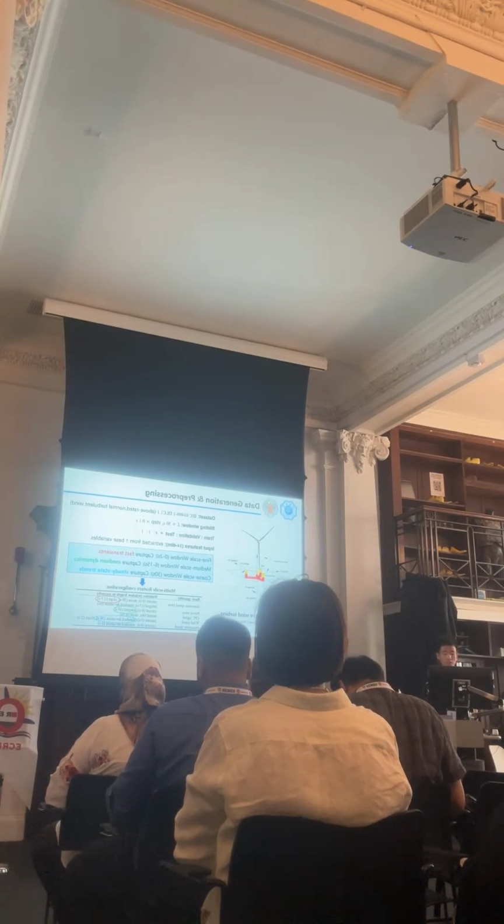And the third one is a coarse-scale window of 30 seconds to capture the steady-state trends, like the standard deviation of the wind speed. With this design, it can meet the different time constants of the wind turbulence, the generator dynamics, and also the pitch actuation.